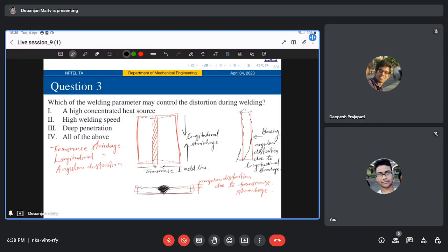So if you are changing your weld metal volume, or your heat input, these act as process parameters, right? Or if you are changing your joint configuration, or the material itself, the degree of restraint applied to the joint will vary. External restraint can be considered to act like a system of transverse springs, with the degree of restraint expressed by the stiffness of the spring, right? So the amount of shrinkage can increase as the degree of restraint decreases.